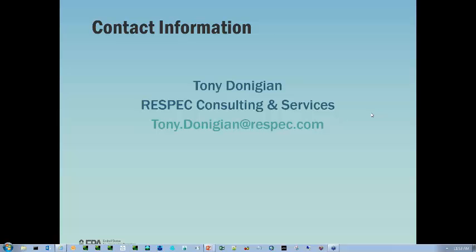Yeah, you can. You really set up the model segmentation or the reach segmentation so that you can output flow values, concentrations, loads, etc., at the endpoint, at the outlet of each reach. So if there is a point where you need information, you would set up your model so you have a reach endpoint there. We have software now that we've been working on for a few years and adding capabilities that make it easier to extract information from the model.